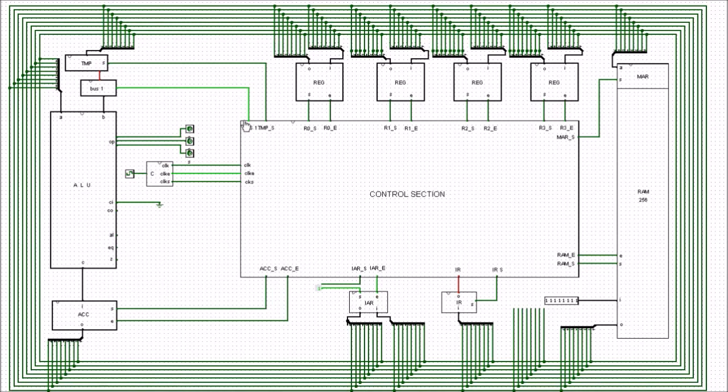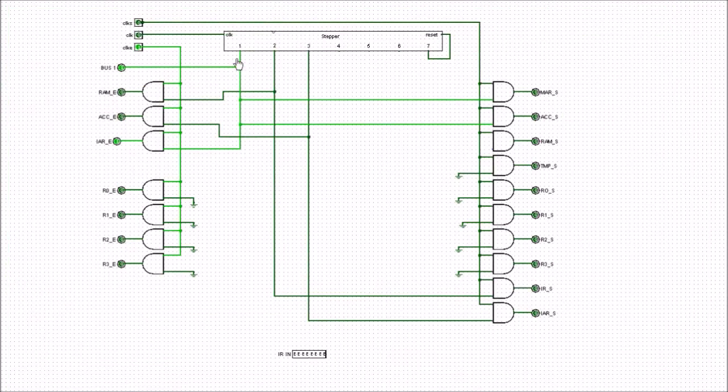So what we're doing is we're getting a value of 1, which in effect is our next address for our instruction, and we're putting it into this ALU here. We've got a value of 1 sitting there, and a value of 0 sitting there, so all the way down this value just sits at 1. This 1 eventually will be passed in and it will be the address of our new instruction. So again, it's just getting ahead of the game.